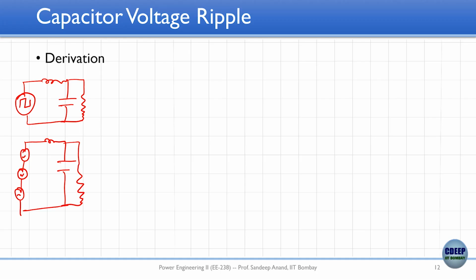Now you have the same circuit, right? Now you apply superposition. In one case you will have only this one source of frequency Fs, in another case you will have another source of frequency 2Fs, in the third case a frequency of 3Fs, right, and then you can solve for it, add those components, and you would get a triangle waveform essentially. So the frequency is the same because the circuit is linear. The shapes will change because there is an inductor and a capacitor, so currents of different frequencies will flow. They may add up and look square, triangle, or some other shapes, right?